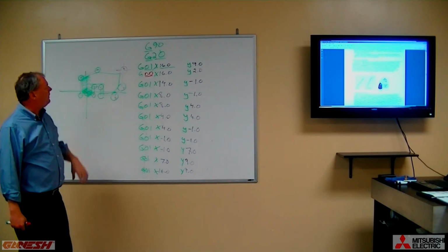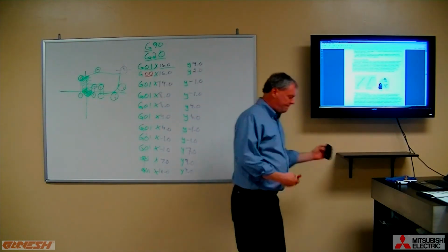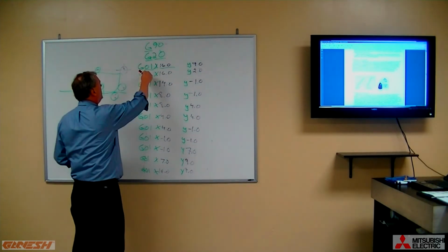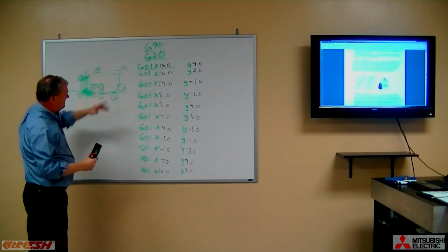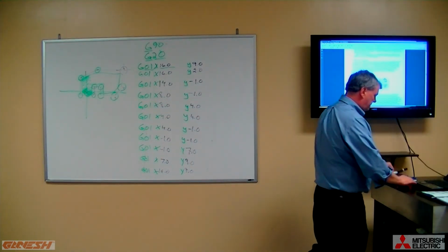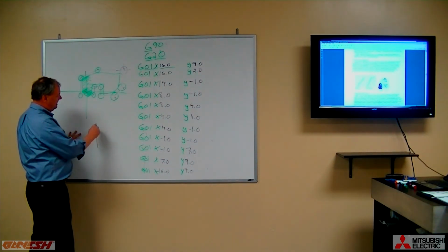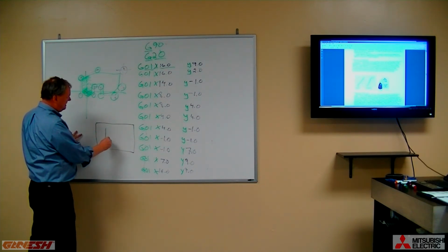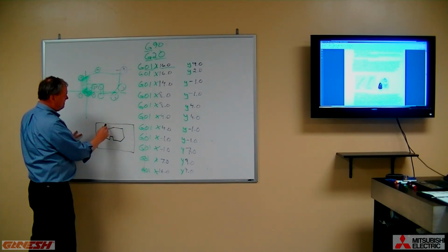So when would it be appropriate to use a rapid or a G00? Well, let's put it this way. I'll change this back to G01. But let's now assume that we have a part sitting on our machine table. So I'll draw that right here in a smaller way. Let's say this is our machine table, and our part is sitting right here on it.